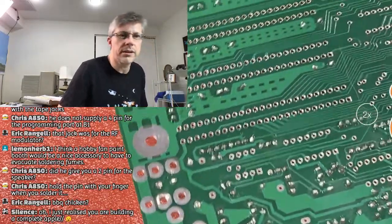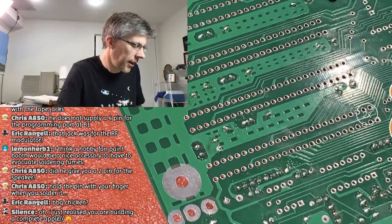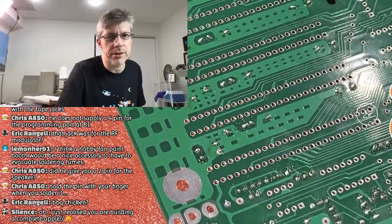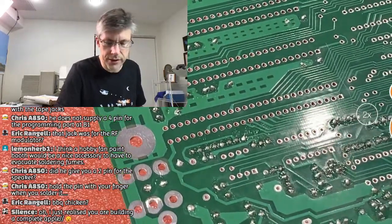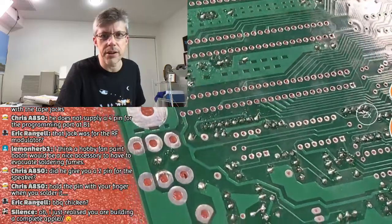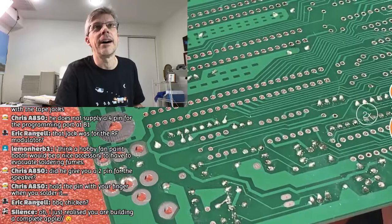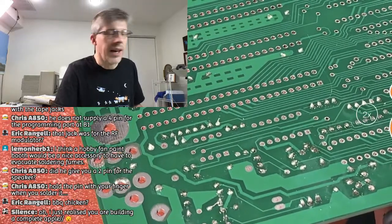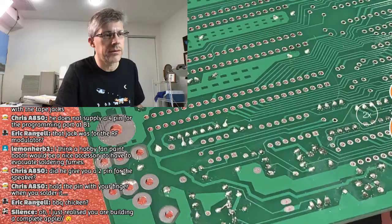So when you're all done soldering, and I might do this actually after today, because at this point I'll have all the capacitors done. It's always good to wash the board to get off all the flux from the solder, and I typically use like 91% isopropyl alcohol. You can use like distilled water, but I don't know if I'd recommend it.